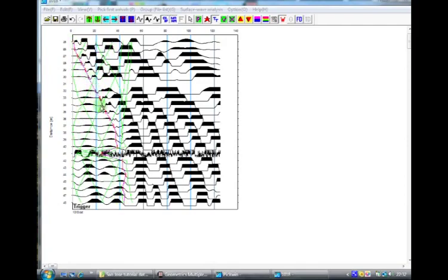The next processing sequence basically will take the travel time information that underlies where these green lines are and this pink one, and it will transform it into what we call a time distance or an XT graph, which is purely a graphical representation of what we see on the screen now. Just remember that when we do this, the first screen that we get when we open our file is effectively twisted through 90 degrees. So what is the y-axis on here will become the x-axis in the next graph that we will see.